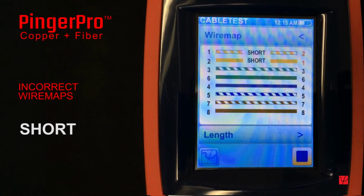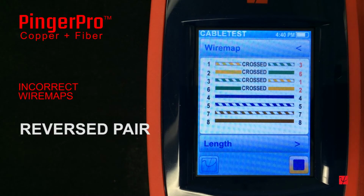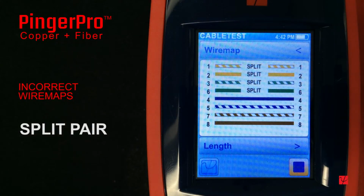A short pair occurs when a wire is physically connected to another wire within the cable or at a connector. A cross pair occurs when one twisted pair, like 1,2, is connected to a different twisted pair, like 3,6. The usual cause of a cross pair is a 568A termination on one end and a 568B on the other. A reverse pair occurs when wires within a twisted pair are switched on one side of the cable. A split pair is the most difficult wire map problem to detect. It occurs when a pair is connected using wires of 2 different twisted pairs.